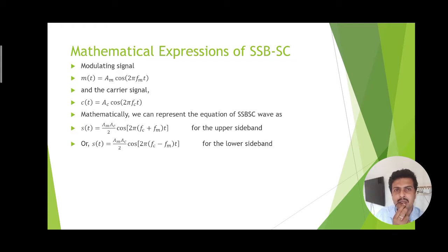Now if we use DSB-FC, we have seen there is an unmodulated carrier, upper sideband and lower sideband. Thereafter DSB-SC has only the two sidebands, not the carrier. And here in SSB-SC, either upper sideband or lower sideband will be transmitted. So filtering plays an important role for the generation of SSB-SC, because one of the sidebands has to be collected properly and that will be transmitted.